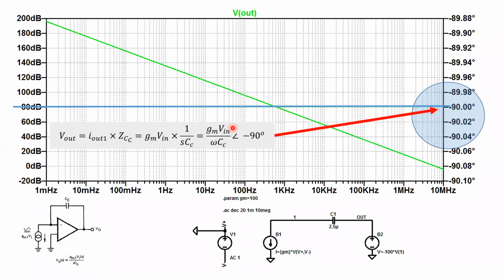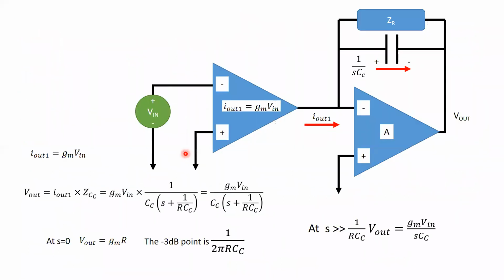So when I'm drawing those straight lines saying here's a limitation of where this op-amp can work, that's because the very first model of an op-amp's frequency response is this integrator, 1 over S type relationship. All right.